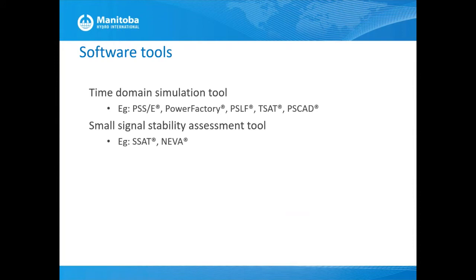In order to do this, you need several software tools. Categorically, they are the time domain simulation tools such as PSS/E, DIgSILENT PowerFactory, PSLF, or TSAT, or PSCAD. PSCAD is an EMT software, others are RMS software.